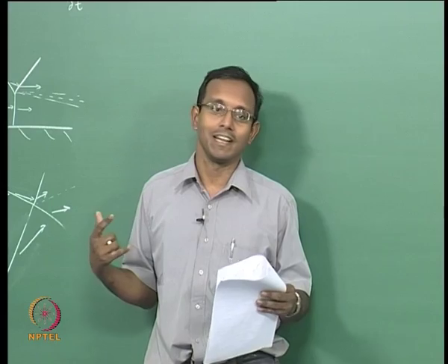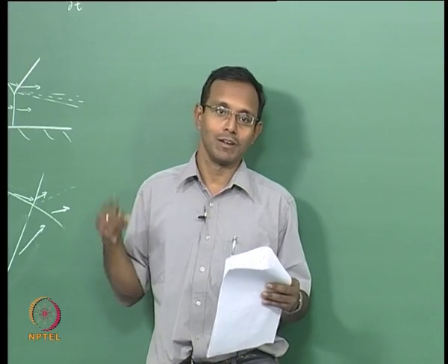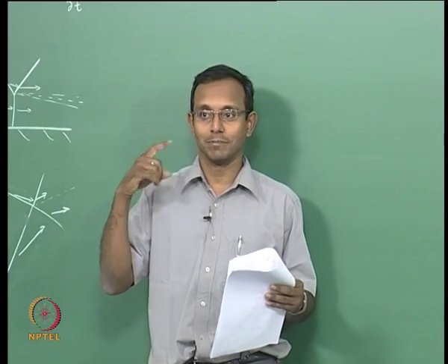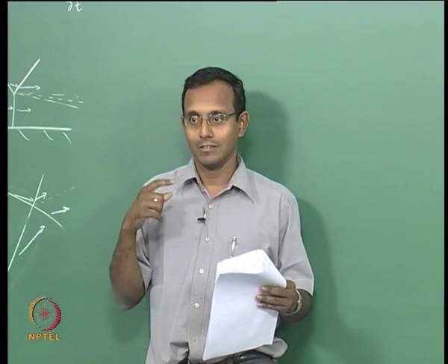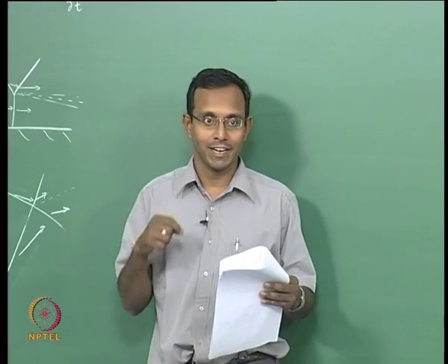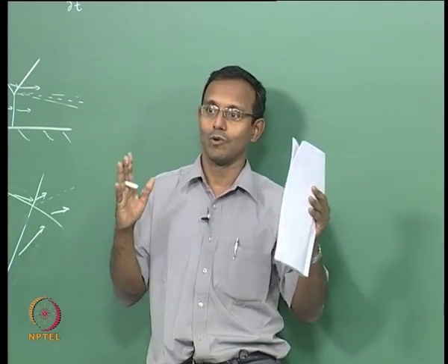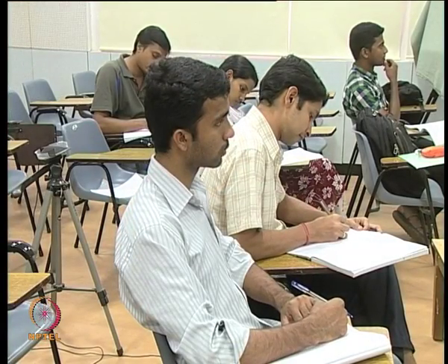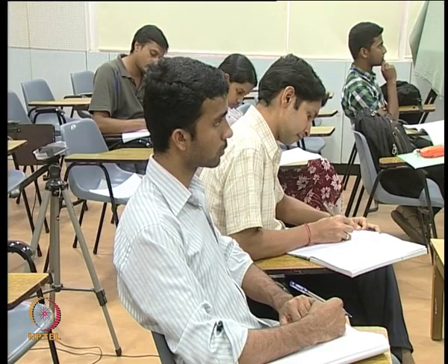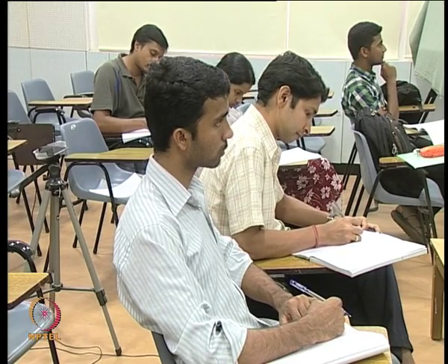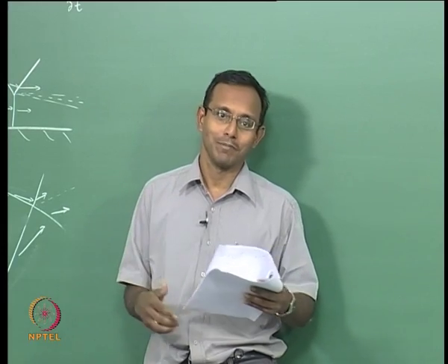So I start neglecting this in my overall bulk, assuming that my bulk flow cross-section area is much more than the viscous interaction area, which will typically be very small if my flow duct is big in size. When my flow duct becomes smaller and smaller in size, they become comparable. You will see that immediately after we derive the whole thing. There is a particular term called hydraulic diameter that will take into effect all these parameters naturally.